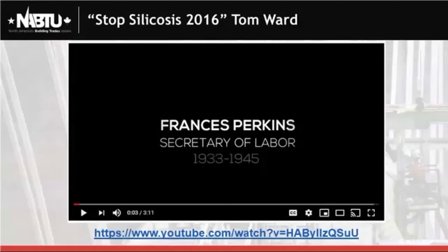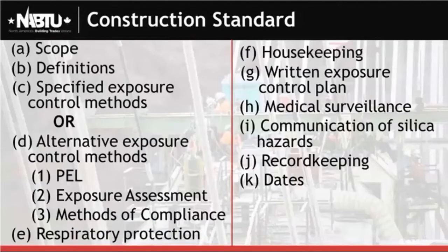Okay, so what do you think? That's a pretty sad story for Tommy Ward. But again, exposure to silica is 100% preventable, just by, like in the video, turning the water on or turning the vacuum cleaner, the local exhaust ventilation, on, which will eliminate any exposure. And it will certainly reduce it to a level that will hinder any health effects.